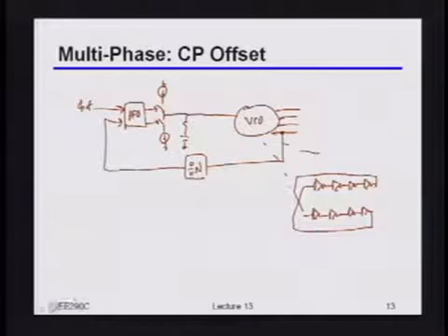Okay? So the basic idea is if I can hack it so that somehow this phase over here changes in some controlled way, then actually I can make it so that all of these phases move together, right? Because the feedback is going to force one of these phases to track with whatever offset I introduced. But then all of the rest of them, because I know it's a ring oscillator, are all directly related to the position at which I put that one nominal phase in the first place, right? So conceptually, does that make sense to people in terms of the trick I'm trying to play?